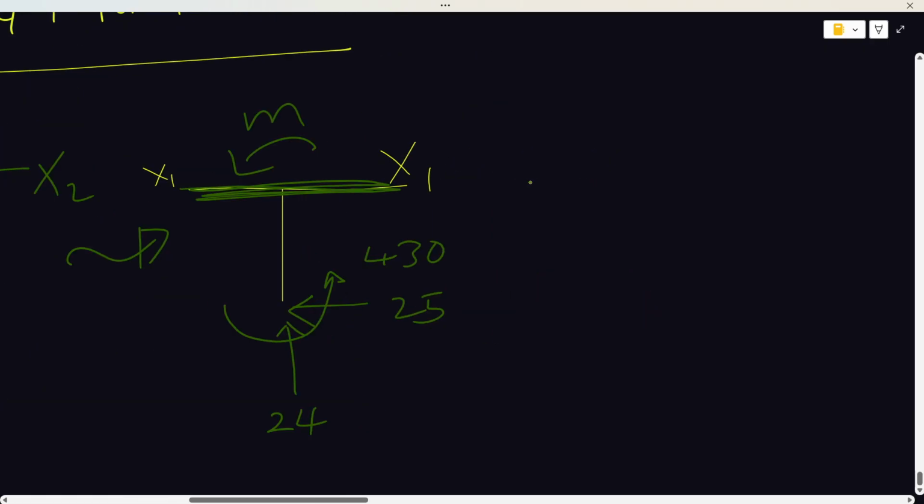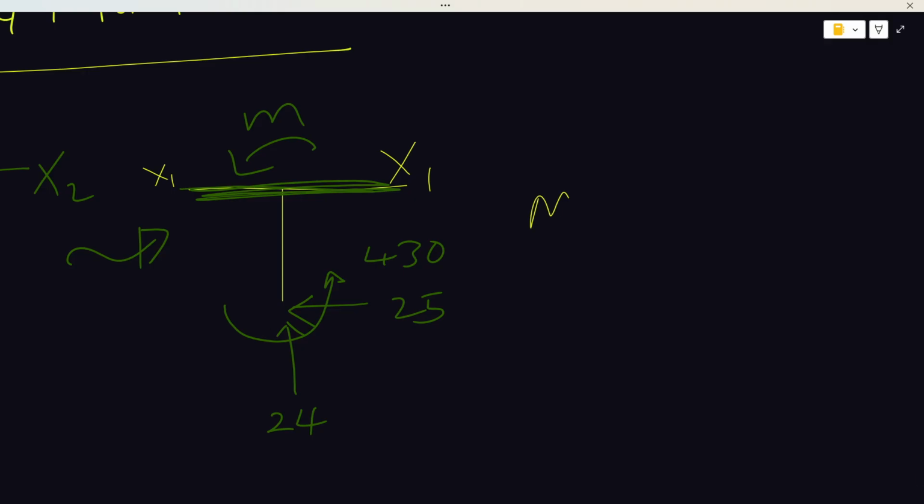So to find the moment for this particular free body diagram that we just sectioned, it will be Mx. You can apply the equilibrium equation and get the same thing, but the convention I normally use when dealing with moments is this: if my couple, my moment, tries to bring my beam downwards, maybe it's oriented in this manner, I'll give it a negative sign when I'm doing my bending moment.